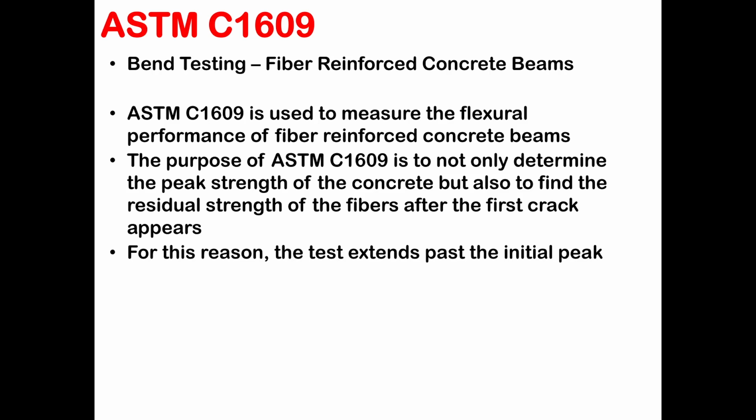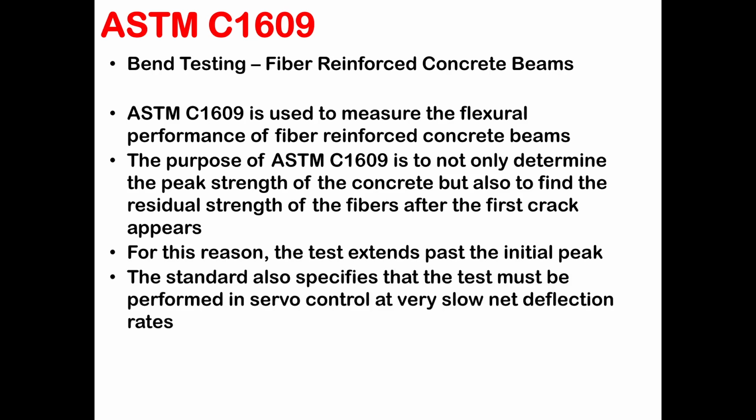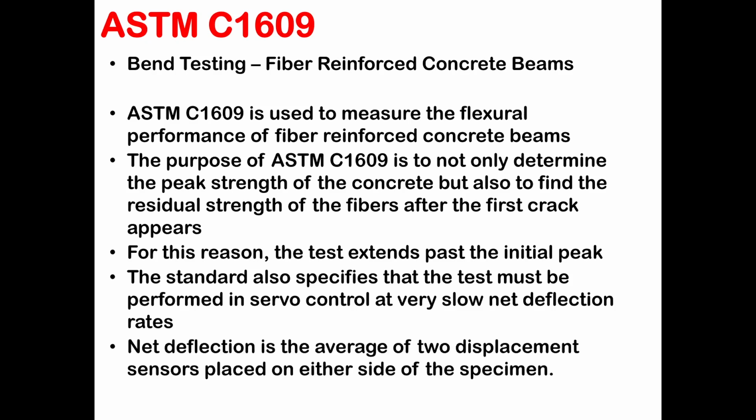For this reason, the test extends past the initial peak. The standard also specifies that the test must be performed in servo control at very slow net deflection rates. Net deflection is the average of two displacement sensors placed on either side of a specimen.